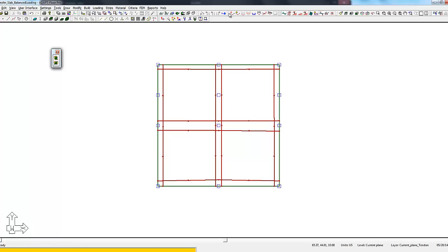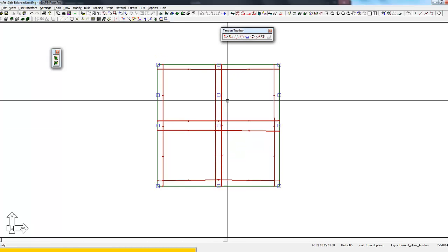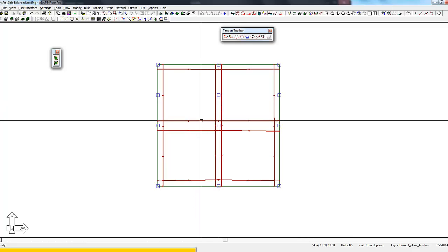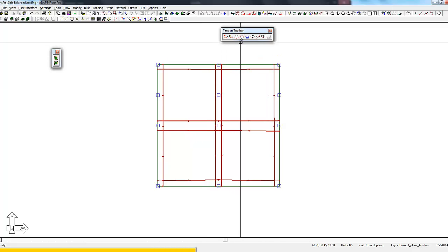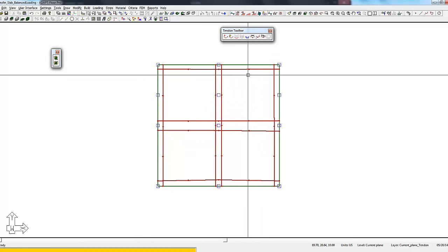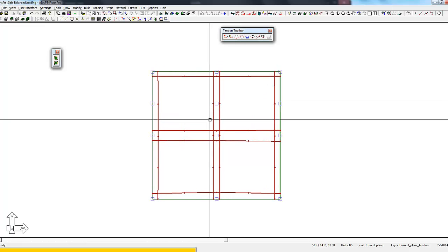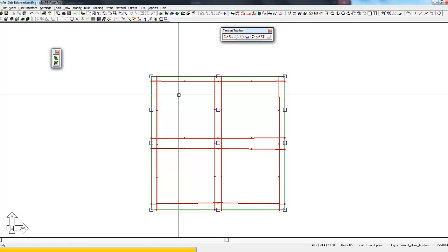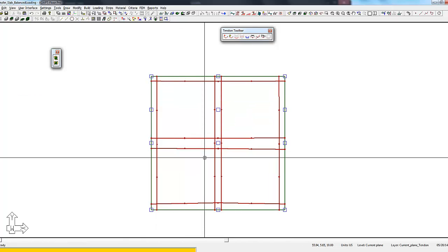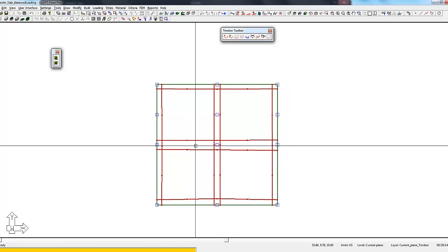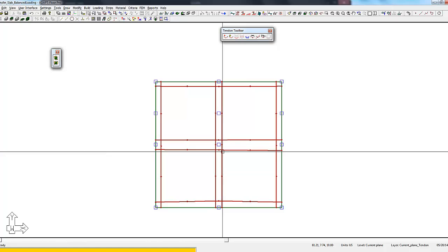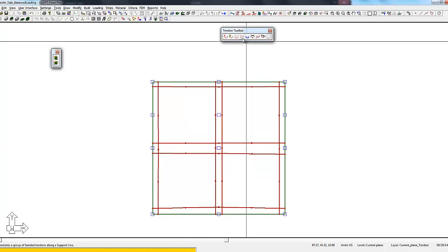These mapping tools on the tendon toolbar are applicable to single level tendon modeling. You can still model this multi-story building and map tendons at each independent level, but the mapping function really applies to what's happening at that specific level. So a lot of times we have to make educated decisions on what the tendons need to be initially, or if we're doing staged construction, what those tendons need to be for each independent stage prior to actually running the analysis. We can again use that tool in an artificial way by increasing that percent balancing on the minimum end to